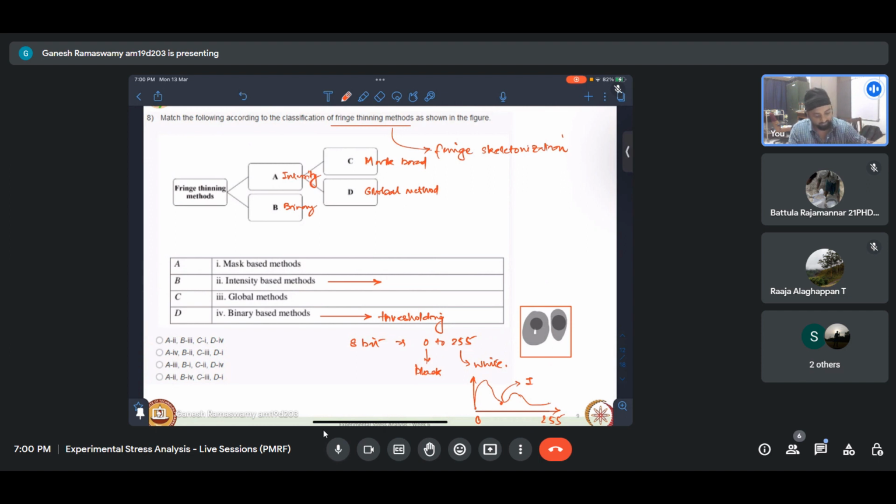Now there is another altogether different way to go about, called phase shifting techniques. Phase shifting methods, where instead of going from the geometry of the fringe features, we will be essentially discerning the isochromatic or isoclinic parameter, meaning delta and theta, delta by 2 pi is n. So delta is retardation and theta is the isoclinic parameter.